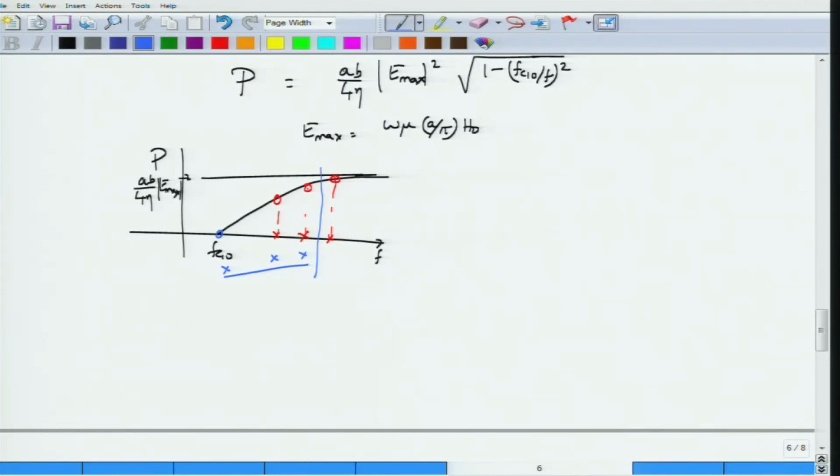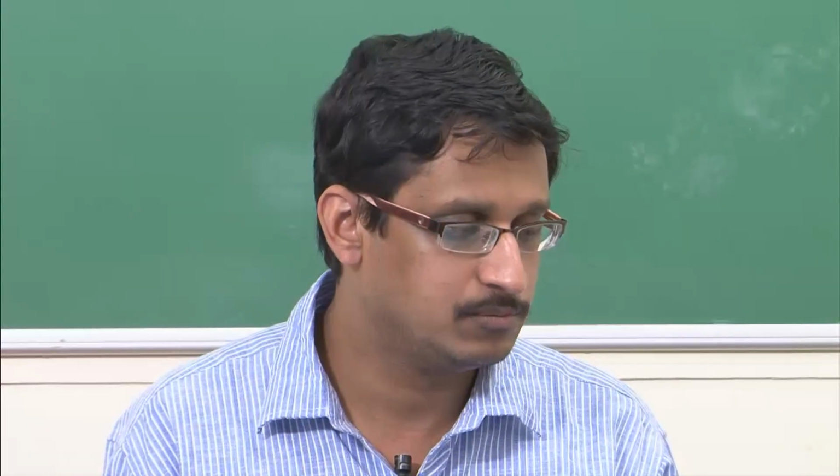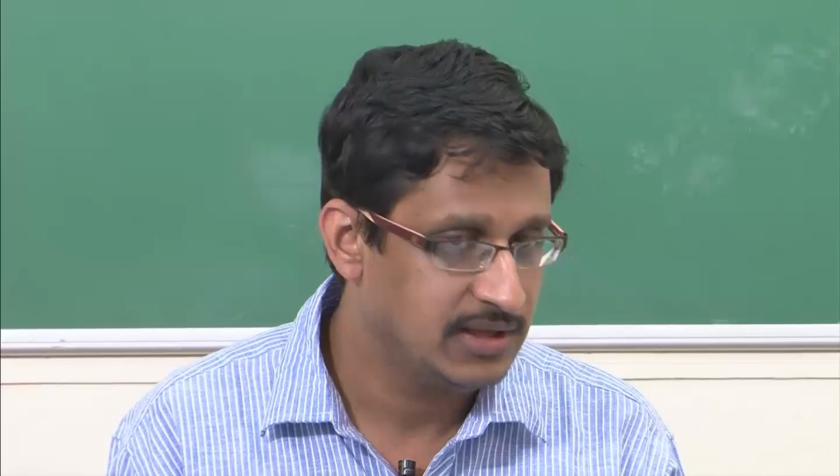So if you want all the power to be concentrated within, you have to operate it only in the fundamental mode, but at that point your waveguide is not actually carrying maximum energy. Okay. What would happen when omega is less than omega c? Well, all the modes would be cut off, right. So the quantities would only be attenuation, and when you launch some power with an operating frequency f less than fc, nothing would be carried by it and everything would be just attenuated. Okay. So we stop at this module and we will consider the power attenuation calculations in the next module.